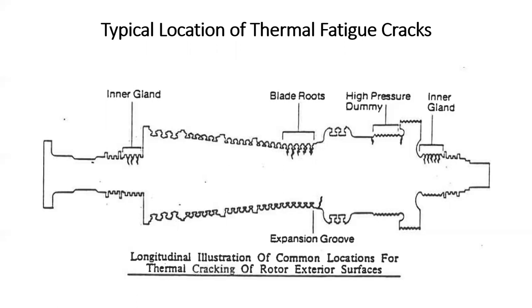There are stress concentration regions, which is primarily where you see those cracks initiate. Probably more on the surface than the bore, but the bore-connected cracks are harder. You have to take the machine apart to find them. And so they're much harder to find and probably more dangerous in the long term because of the difficulty in knowing that they're there.